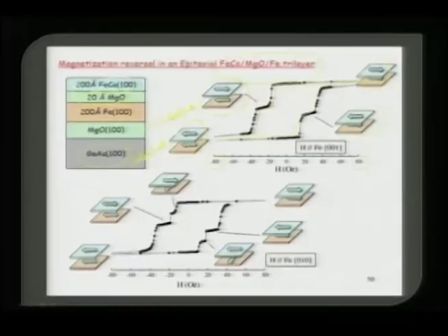So in any TMR device you should see a staircase-like property, which is a signature that you have made the device. The same is true if you measure along this axis and along this axis; here a double staircase phenomenon will come. That is because this moment, this spin, is rotating, therefore you see a double staircase situation if you measure along the 0 1 0 plane.